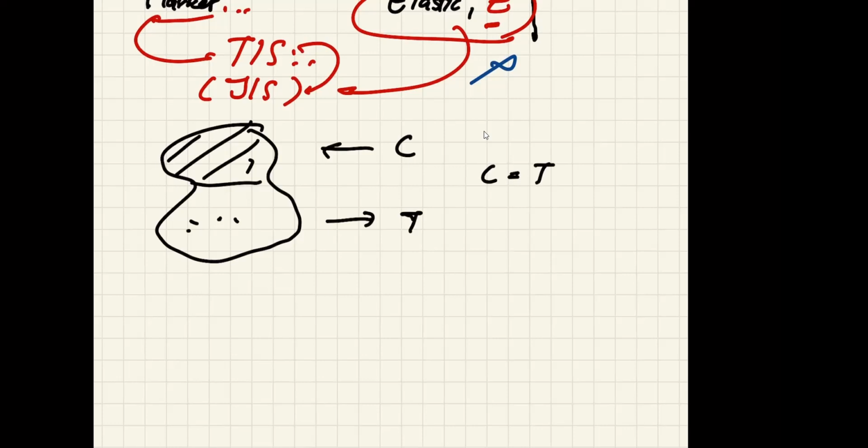And the force here, because the stress is like a block, is Fy throughout. So I can say that Fy multiplied by area under compression must be equal to Fy multiplied by the area under tension.